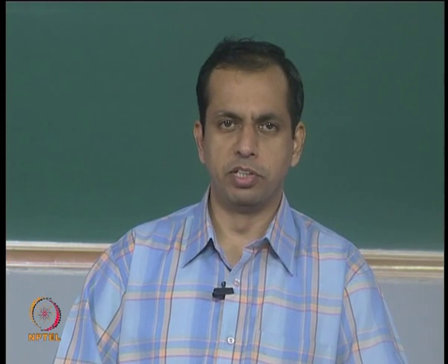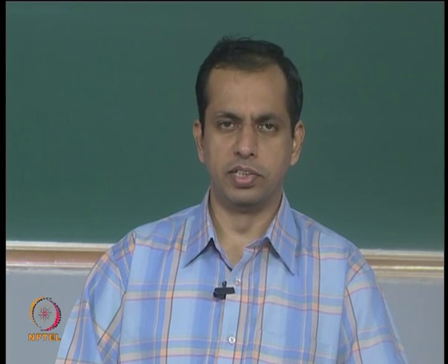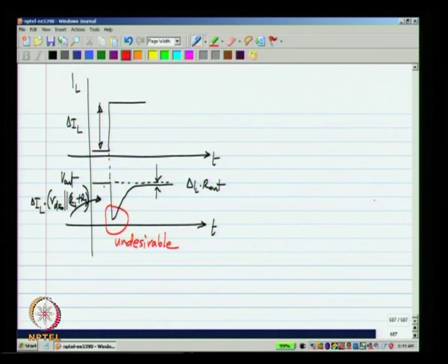How much it changes depends on the size of the capacitor, but by using a very large capacitor you can reduce the change. So, instead of having this large dip, what will happen is that the output voltage will start to reduce as a ramp and it will go on reducing until the feedback effect kicks in and it will do that, okay.